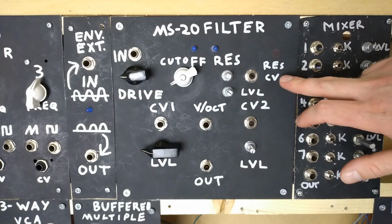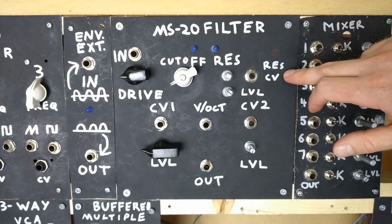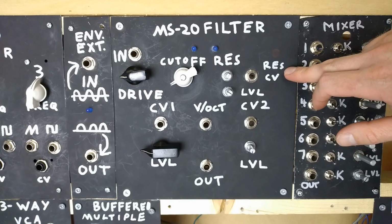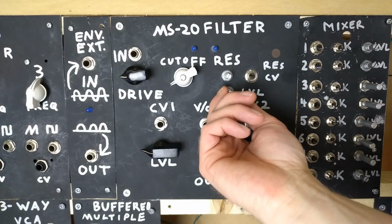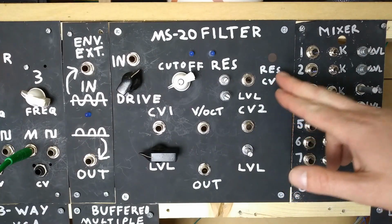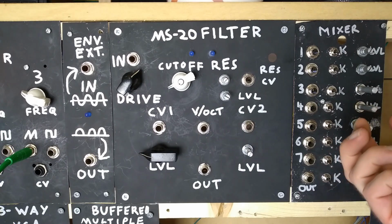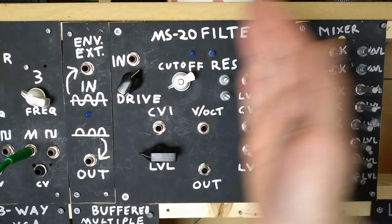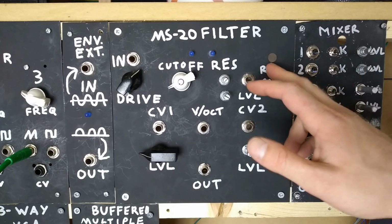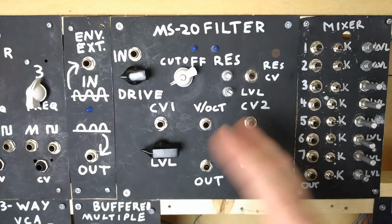Another feature that I've added is this Vectoral-based resonance control, where we can modulate how far we push the filter into self-oscillation, which also has a level control. And then finally, the output. You will also notice that there was this random hole just here. That's because I'm planning to add a high pass input, so we can use the filter to cut off the low frequencies. But that's a project for another day. So without further ado, let's finally start to hear what this thing actually sounds like.